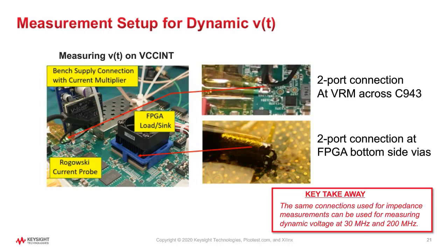The coax connections are 50 ohms, which is high compared to the power rail impedance, providing a high impedance probe connection. The oscilloscope calibration to deskew the ports and fixture cables with matched length and equal delay ensure that the dynamic voltages are measured simultaneously.